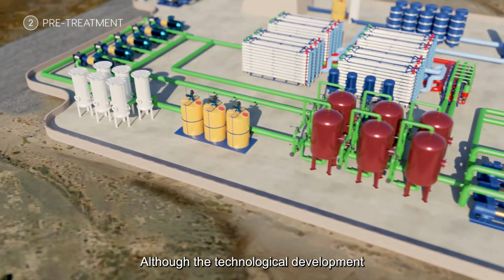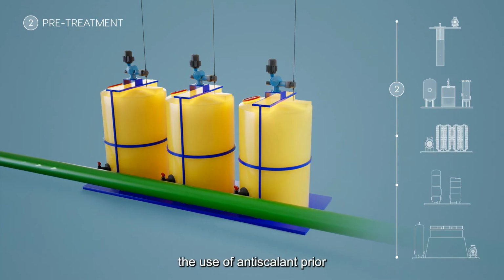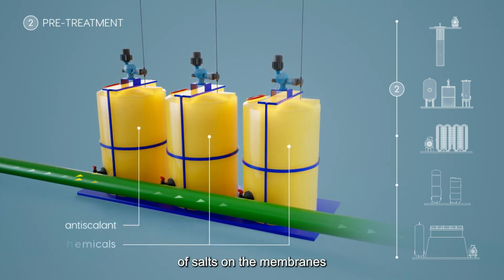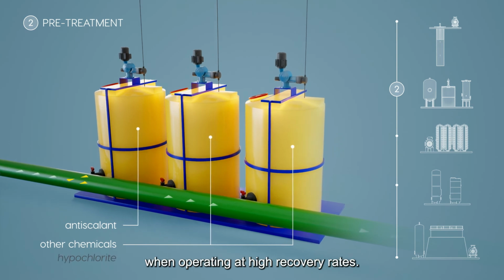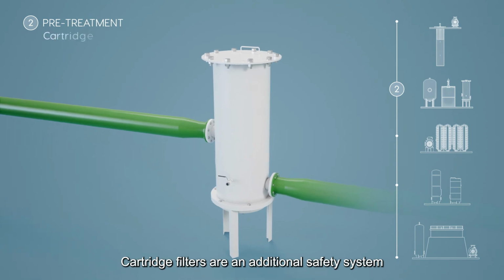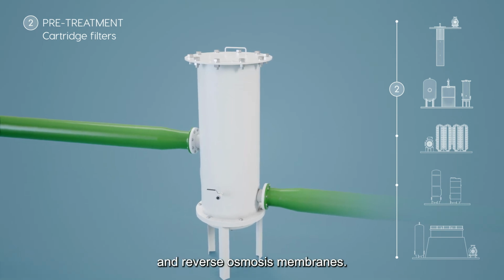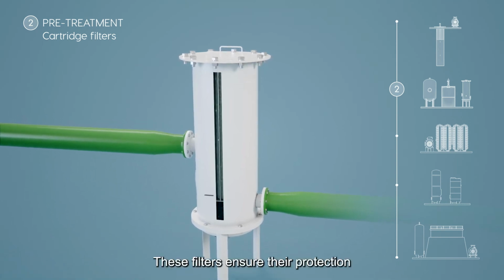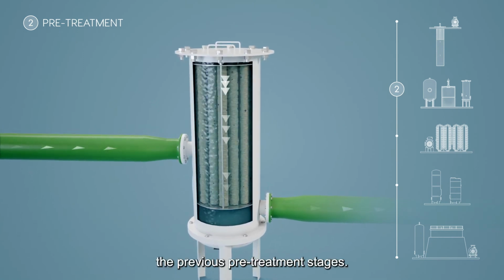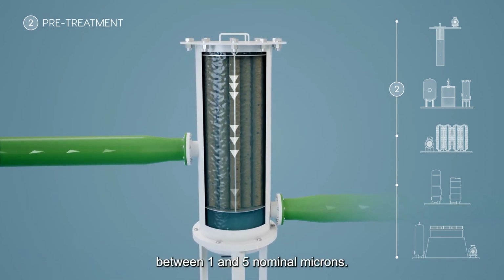Although the technological development of reverse osmosis has made it possible to reduce the use of chemicals, the use of antiscalant prior to the process is still common to prevent the deposition of salts on the membranes when operating at high recovery rates. Cartridge filters are an additional safety system that is installed upstream of the pumps and reverse osmosis membranes. These filters ensure their protection by retaining microparticles that have passed the previous pre-treatment stages. Their filtration size is normally between 1 and 5 nominal microns.